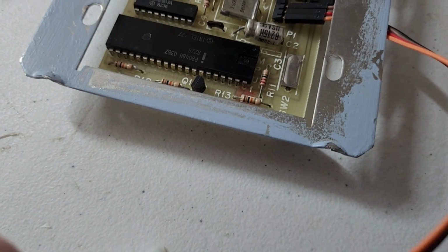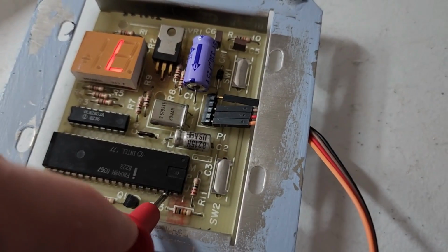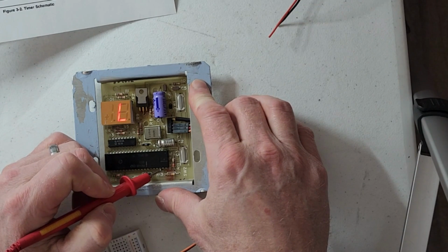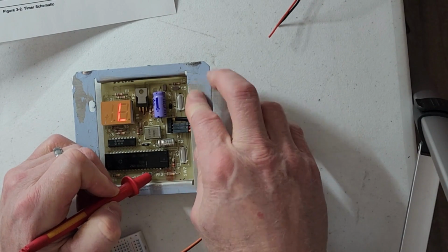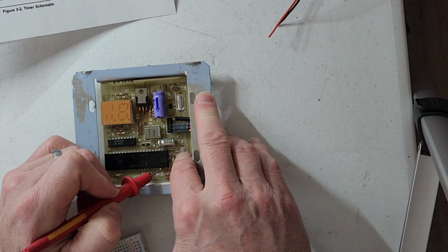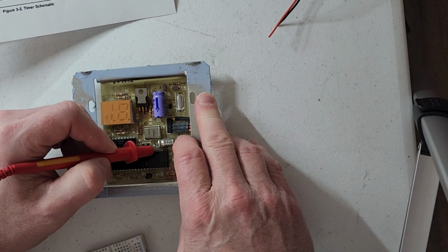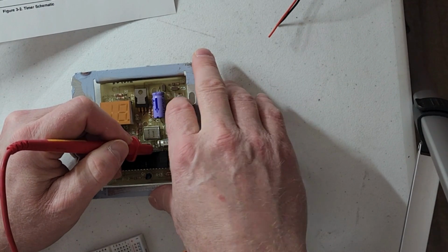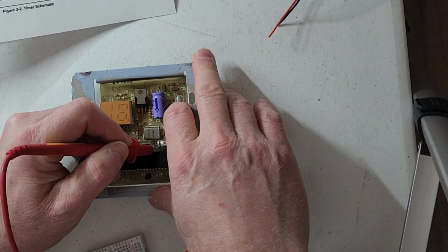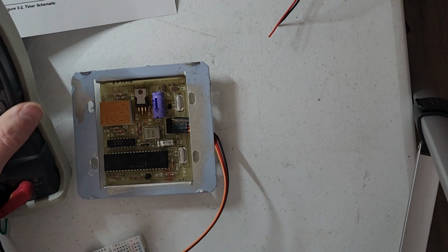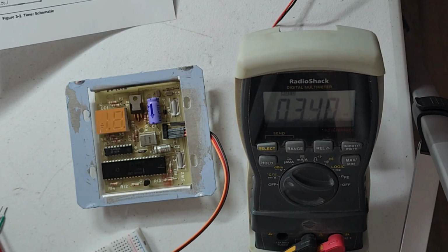I mean, obviously the buttons are working because this switch goes to here. Hang on, let me get the camera set up on the tripod. So where was I? I know pin 39 was connected to one of them. It's at 4.8 volts right now. Oh yeah, when I press this switch, it goes to 0 volts. So that's working, and I believe pin 1, which is tied to pin 1, is also sitting at 4.8 volts and goes to 0 volts when I press the switch. So the switches are working, which I figured they were. It's just like this thing's not.